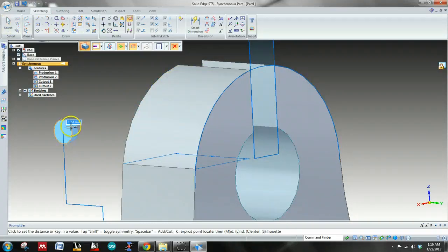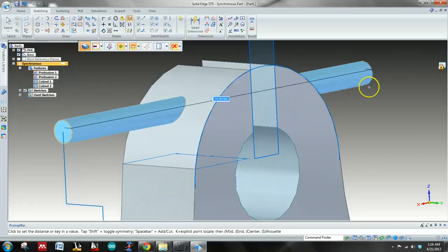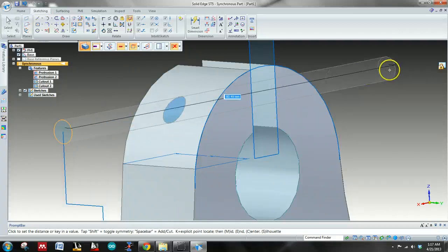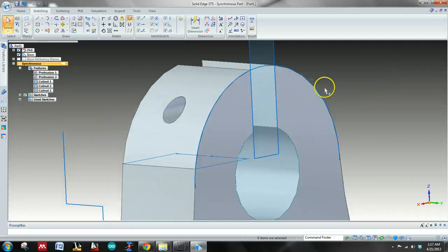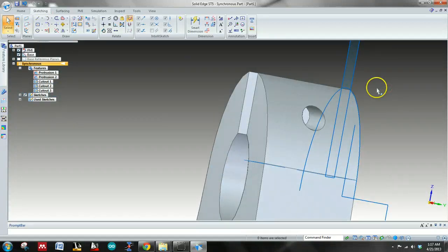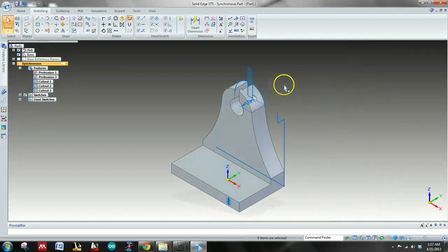That's okay. We just click that little arrow, and you'll see here that we're adding material to this thing. We don't want to add any material. We want to take material away. We want to drill a hole. So you'll come here to the extrude, hit remove, and now you see that we can go ahead and cut through this thing. So I'll just cut through it right now. And now we have that circle there, or that hole, I'm sorry.